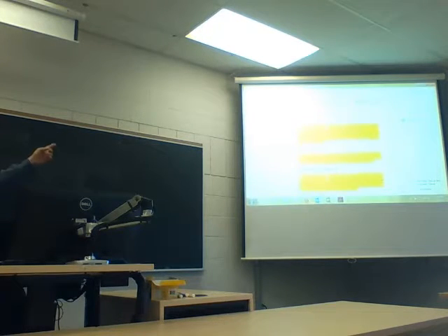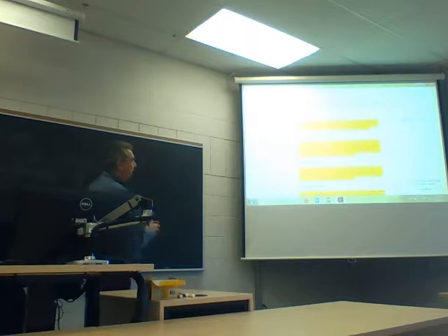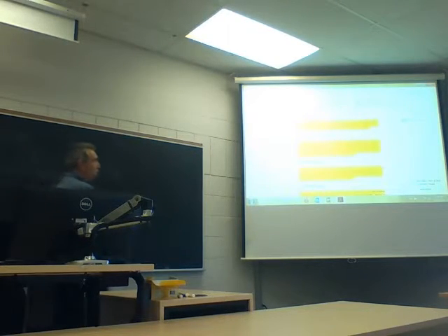So this is the packing system that they're talking about up there. This system consists of a radiator type cooler, accompanied with electric powered fans. You all know what a radiator is in your car. Same idea. The radiator type cooler is split in two sections. Compressor fluid is circulated and cooled in one half of the cooler. Discharged compressed air is cooled in the other half.